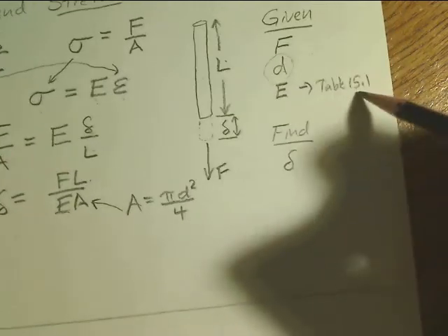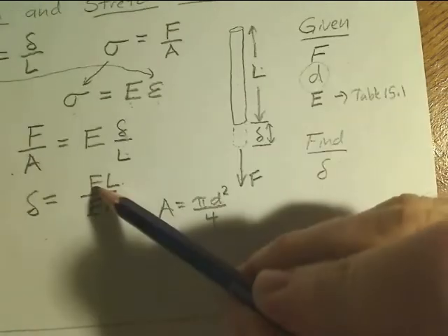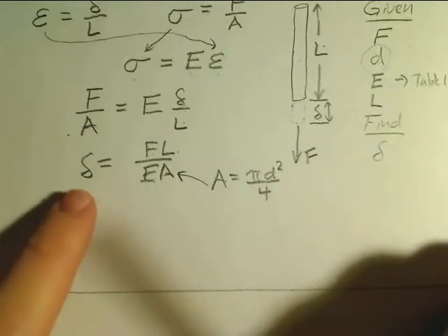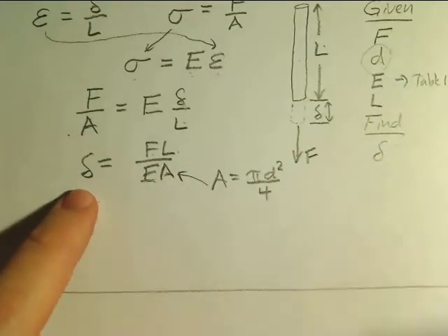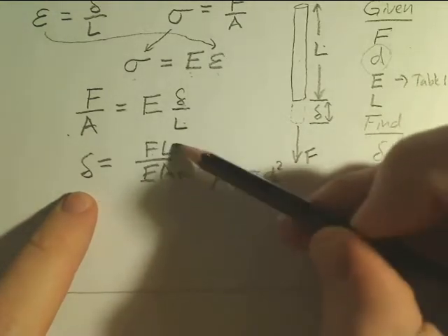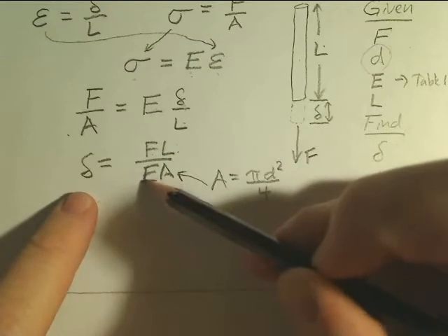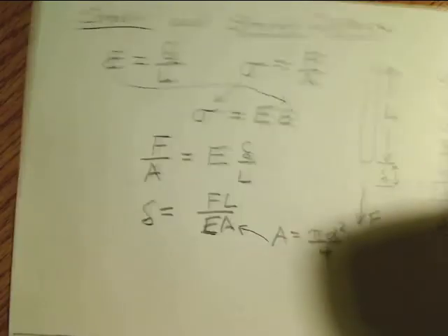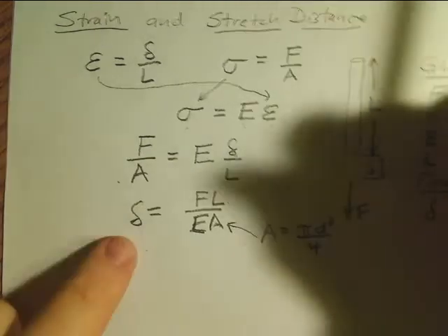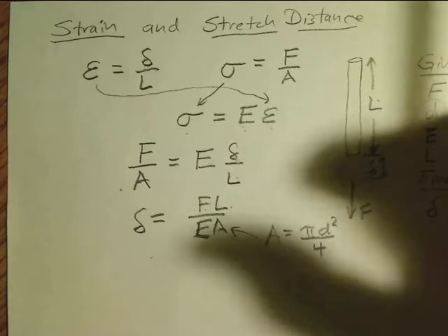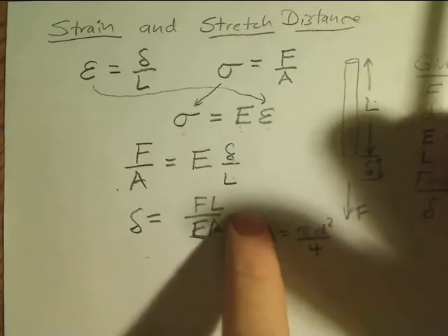Modulus of elasticity in table 15.1. Force over there. And I guess they're going to have to give you the length on this to figure out how much it will stretch. So you put this in pounds. This is in inches squared. This is in inches. This is in pounds per square inch. The answer will come out in inches. Okay. So the point, again, is to find the stretch based on how much force, the type of material, and the length of the material you have.